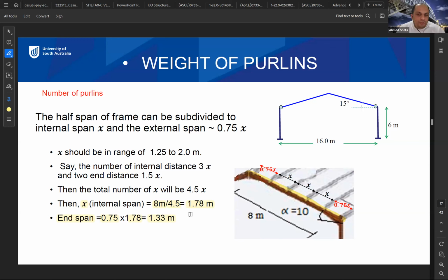Yeah, if you want to go for this detail, it will be the width of the sheet that the manufacturer sends to the site. So each roof sheet has a width of the sheet itself. Oh, okay. Yeah, no worries. So this will be the maximum spacing for the purlin. Yeah, okay, that makes sense.